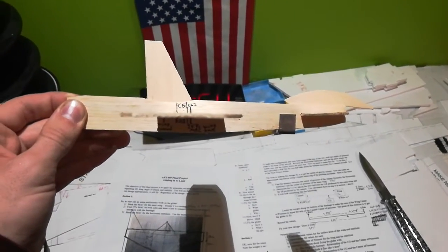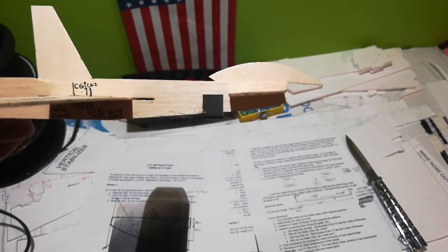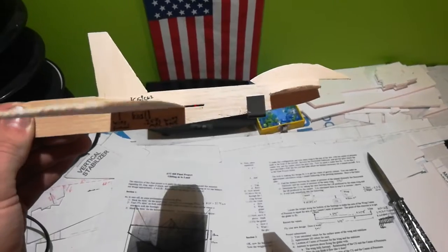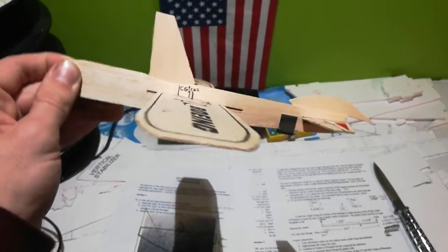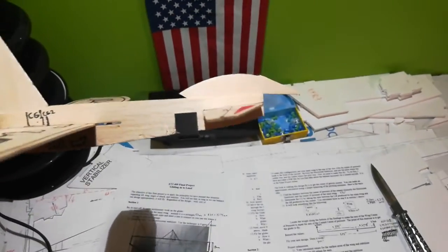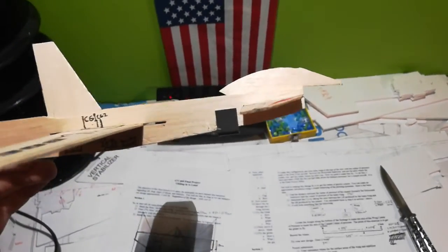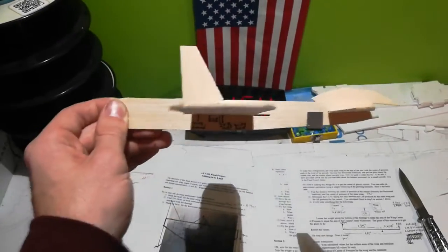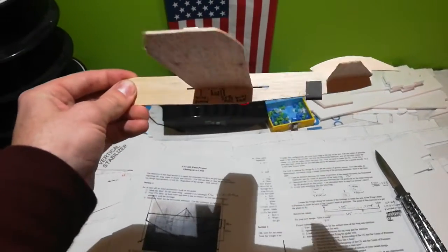because like with large airliners, having the extra weight in the back means they don't have to use the elevator as much at a negative pitch to keep the nose up. Instead, they can have that weight do that, which means there is less aerodynamic drag induced by the negative lift of the horizontal stabilizer. That's just an extra little detail, but that should cover everything for my final project.